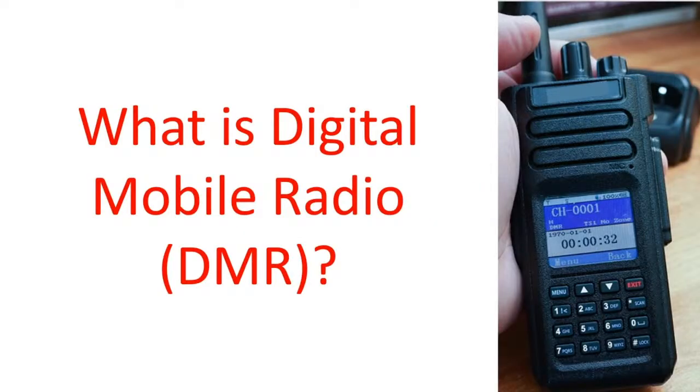Digital mobile radio, known in short as DMR, is the digital counterpart of conventional analog radios. It uses time division multiple access or TDMA technology for transmission. As it uses TDMA technology, it can operate two slots in a conventional 12.5 kHz channel spacing.